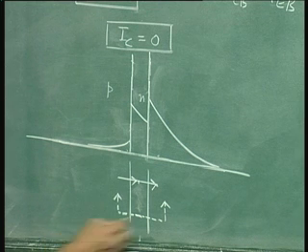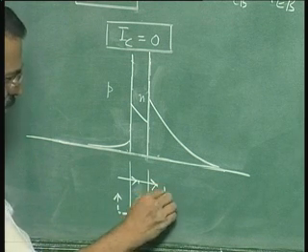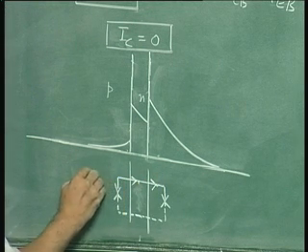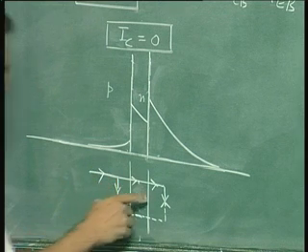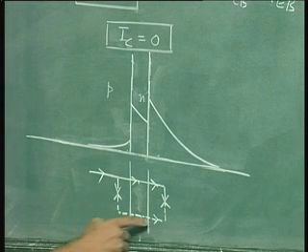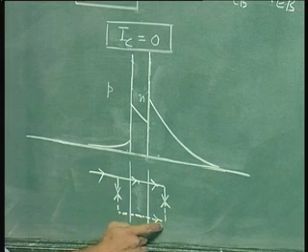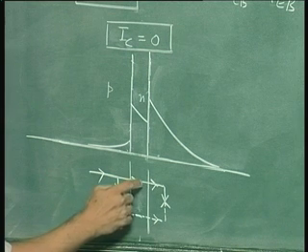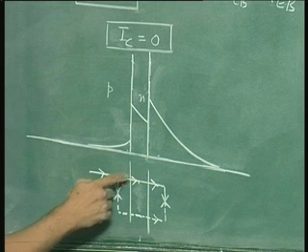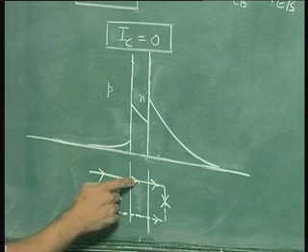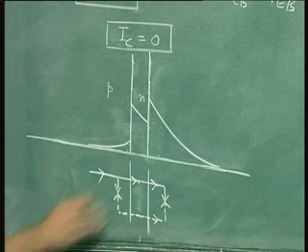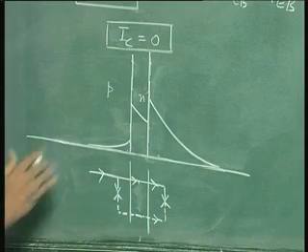Now to complete the picture, these electrons have to recombine with holes, so you have this, and these electrons have to recombine with holes, so you have this. So this is your emitter current, and now what you find here is very interesting. You have electrons being injected from base to collector. You also have holes being injected from base to collector. These holes are coming because they are injected from emitter to base, and recombination in the base is very small, so most of them are coming into the collector. So you have holes and electrons moving in the same direction across this collector junction. That is a very interesting situation.